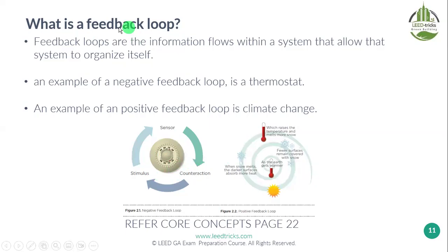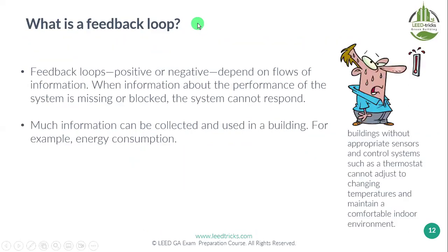Okay. What is also a feedback loop application in our building? Sensors. Sensors in our building. Motion sensors, CO2 sensors. When you reach the CO2, let's say a densely occupied space. One space is very occupied in your building. So the feedback loop is very important here to know when you give ventilation, when no. Not giving just random and excessive ventilation, which consumes more energy. Okay. So this is the feedback loop in a simple way.